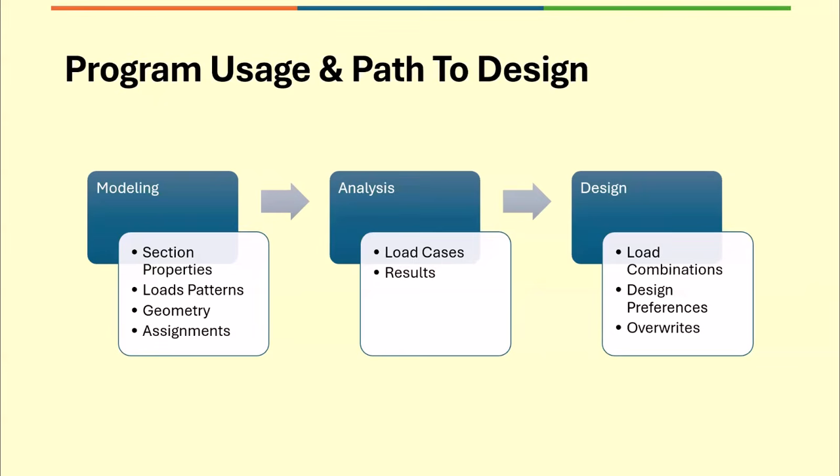And then we'll perform the analysis for various load cases. The results of these cases will be reviewed, and accordingly actions will be taken, either to reiterate analysis by updating properties, or the results are fine to proceed with the design. So design is the last stage. It's a post-processing thing where we have control over the load combinations to be involved for the design, and design preferences and overrides if any needed.